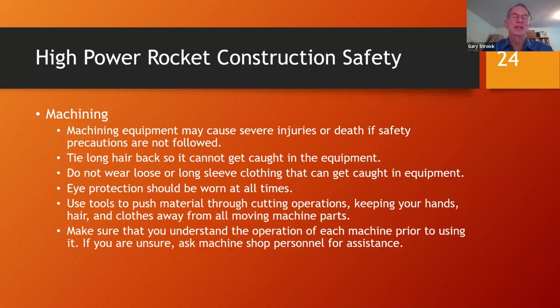There are certainly incidents that have occurred where somebody has gone into a school machine shop, for example, to work on a machine late at night, and they got their hair caught in the lathe and it choked them to death. So it can have very serious consequences. So really try to do this in pairs, at least, and certainly have people there to watch what you're doing. Yes, very good advice.